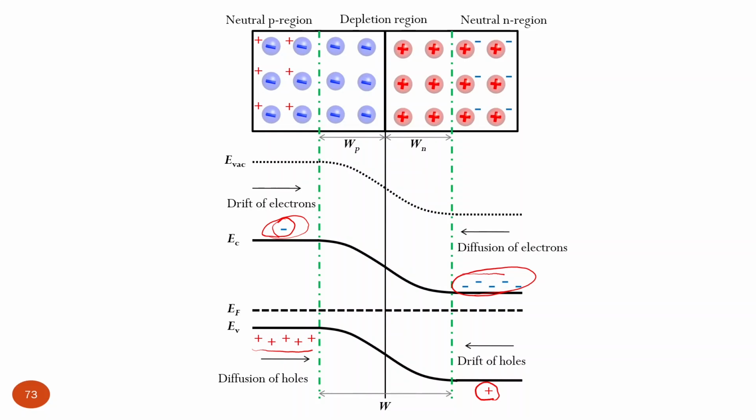They reduce the diffusion rate, so that this diffusion current becomes equal to the small drift current, and they go in opposite directions and compensate each other. So what's the reason why the diffusion current of majority charge carriers does not contribute much and remains small?